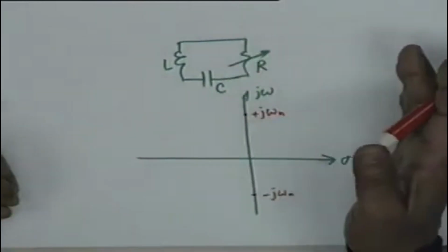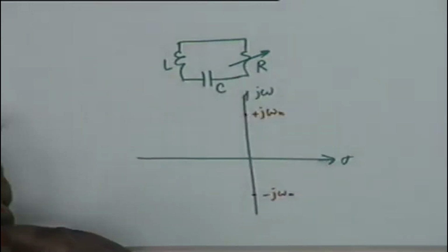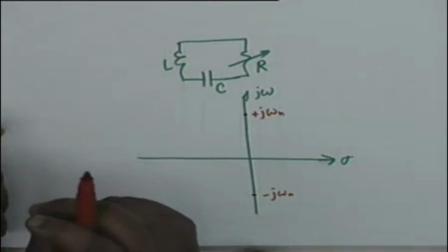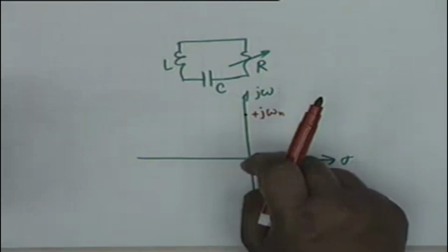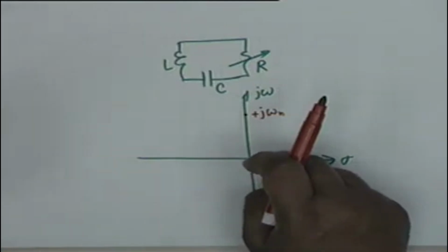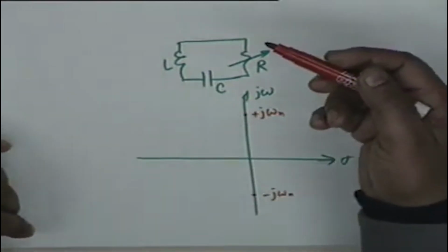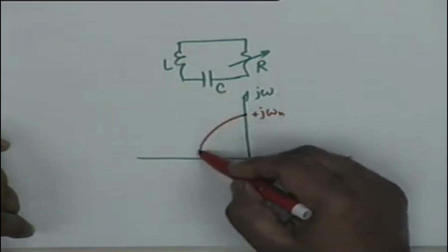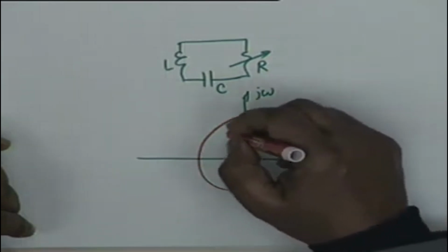This is the right half plane, this is the left half plane. They move to the left half plane such that the distance of either root from the origin remains a constant, and that constant is equal to omega n, and therefore the movement of the roots shall naturally be on a semicircle where this distance is omega n, alright.